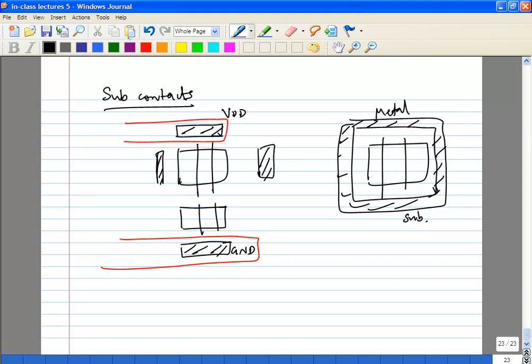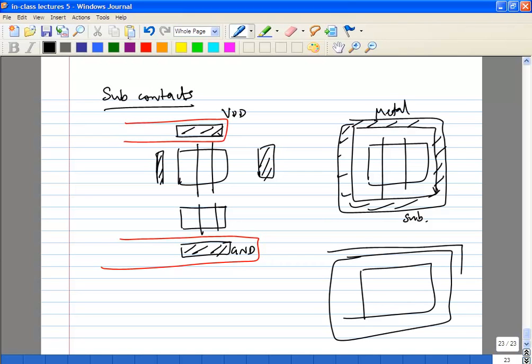And then they'll be connected to ground on metal. So you'll be giving a very good contact. That's the idea. Okay. Now, let's say you have built your circuit as a block. Around your overall circuit, it's actually not uncommon to put what is called a guard ring.